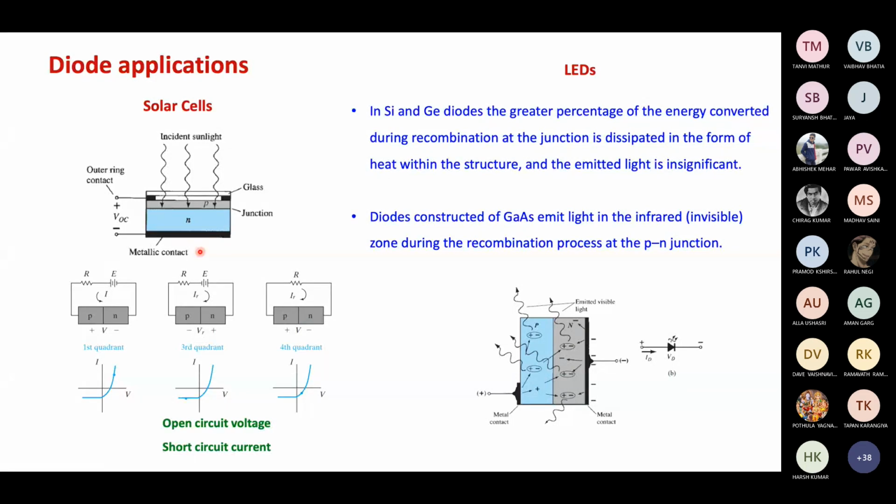So, sir, we have designed a circuit in which the photodiode is operating in reverse bias, and when light falls, the voltage on the n side will drop or it will increase. Like, if I take a reference of 0 volt on the n side, and when light is falling, will the voltage go negative or will it increase to 1 or 2? No, what are you maintaining constant? Are you maintaining the voltage constant across the diode, or the current constant across the diode? The voltage constant. So if there is a fixed battery applied,